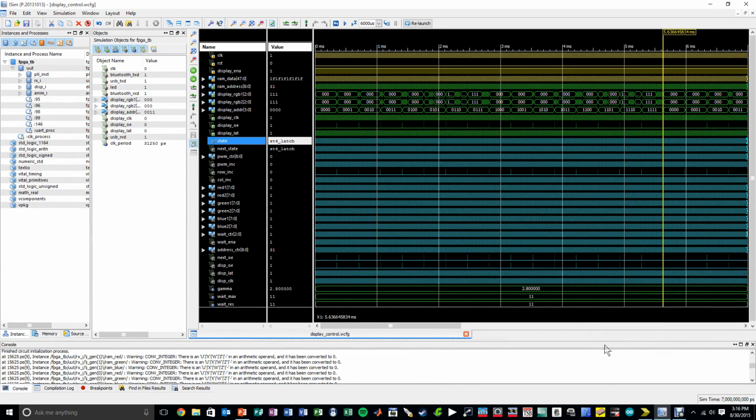So let's talk a little bit about the PWM. Now obviously a lot happens while you're writing line 0, for example, or line 1 and line 2, because there's a lot of activity in between the different lines. And I guess the reason for that is because you're doing PWM. So that means that you're doing your PWM display within each line as opposed to within each frame.